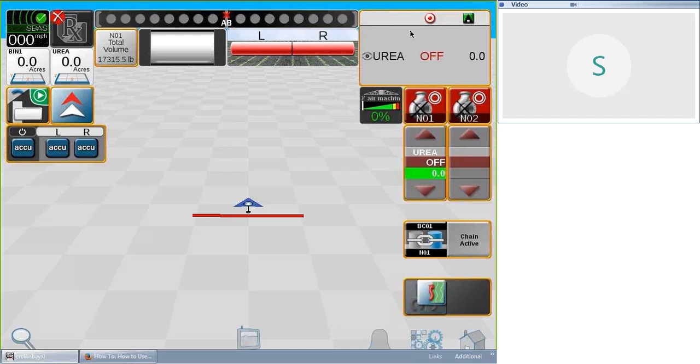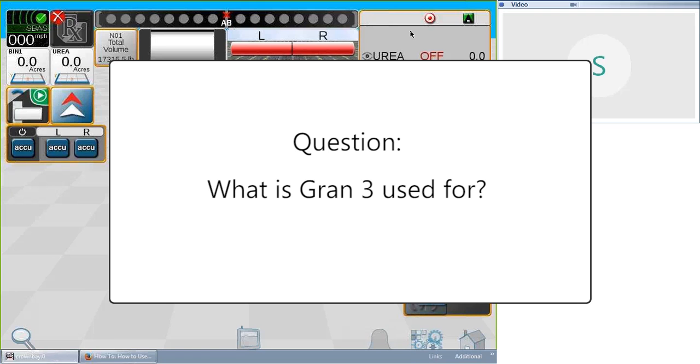As far as the Slingshot side, to upload those RX maps to Slingshot to send them, you do have to make sure they're zipped up prior to bringing that file into Slingshot. You can't just bring in the raw files. They have to be zipped up, and you can zip more than one RX map together, but you do have to make sure all the correct files are together in that file. So you can do one at a time as a zip file, or you can do them all as a zip file.